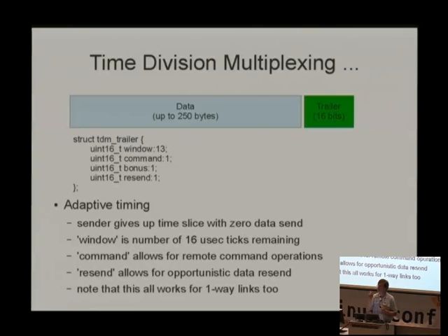Right? Which means you actually only have a very small period of time where the ground station has grabbed the transmit token, if you like, and is transmitting, and you end up with a practical efficiency from the air data rate down to the data you can actually get through of about 85%, which is not bad on a bidirectional link.